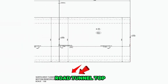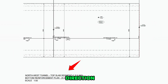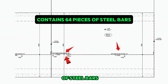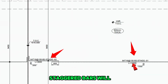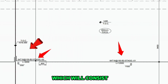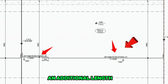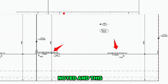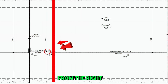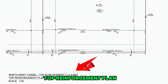The underpass road tunnel top slab segment 1 bottom reinforcement plan in the X direction contains 64 pieces of steel bars with a spacing of 150 millimeters, and B2 staggered bars will be used, which will consist of 2 pieces of steel bars. Along with this, an additional length of 3,000 millimeters will be added with an overlap noted, and this will also be provided from the right side to the left side.